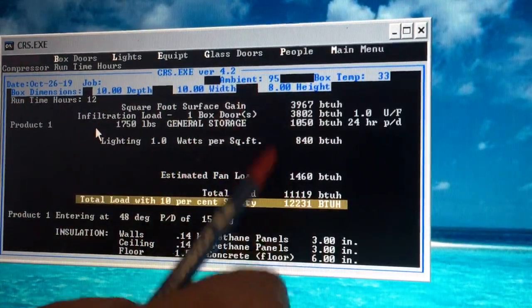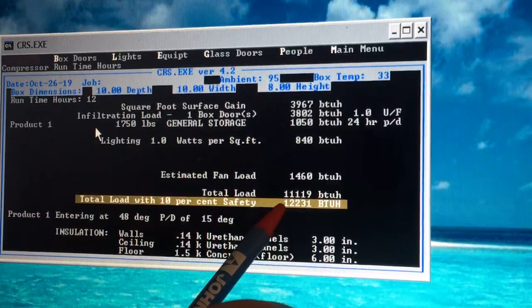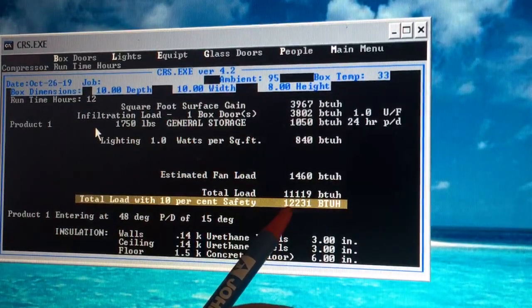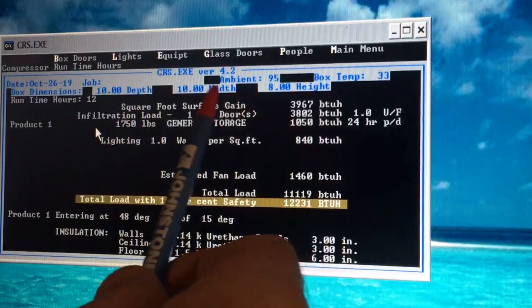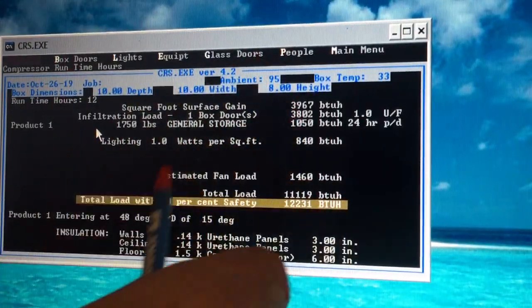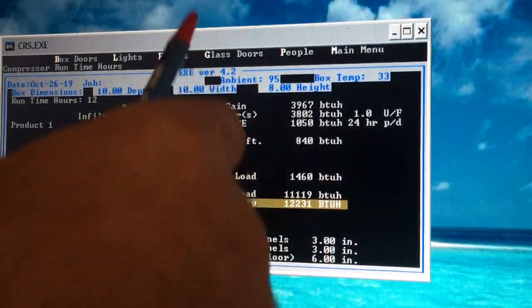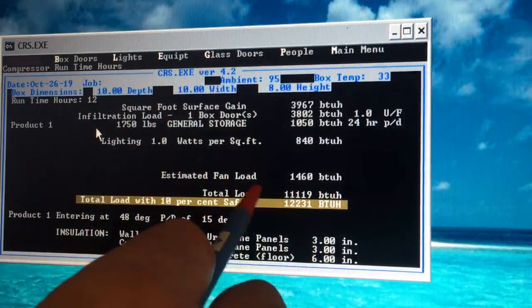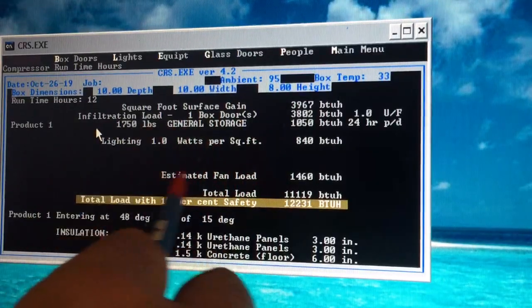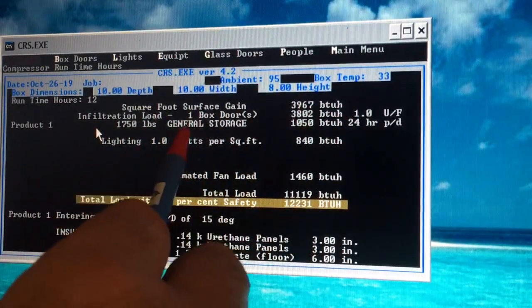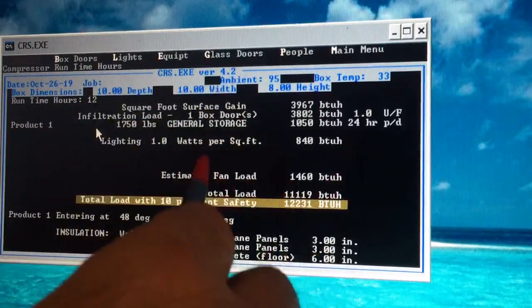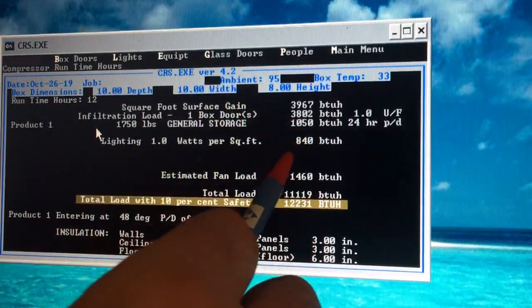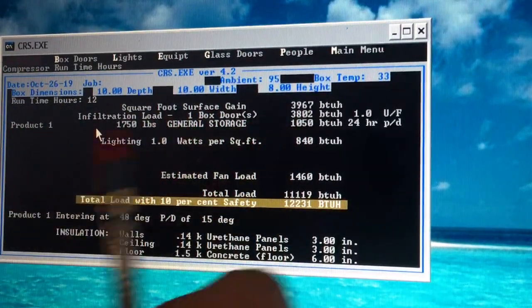You put a bigger evaporator, bigger compressor. You put in a 12,000 BTU. Now it's going to do the job quicker, with a 12-hour runtime. The only time you get into problems is if you size it way too heavy, like 200% heavier than you need, then you could get into short cycling issues.